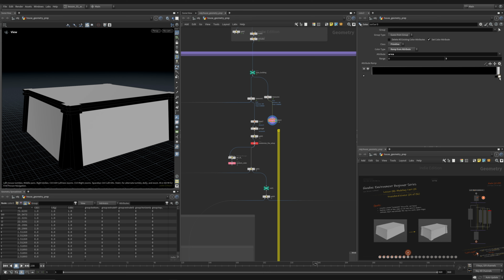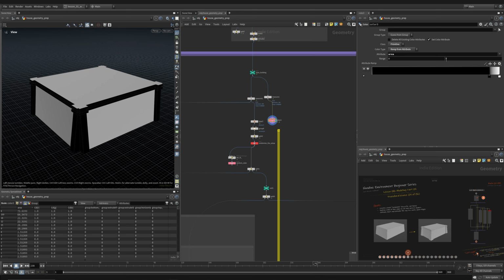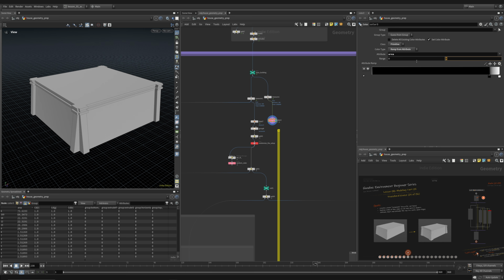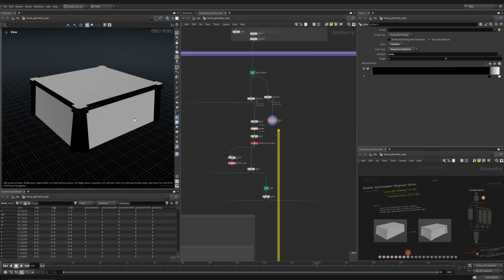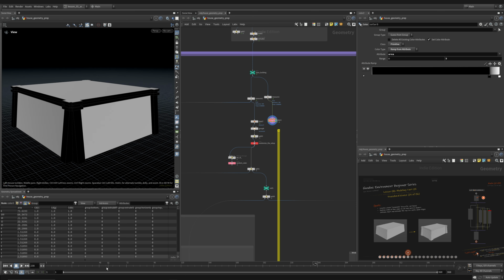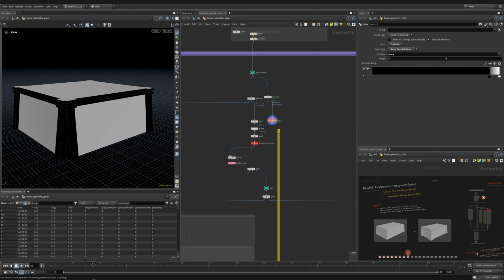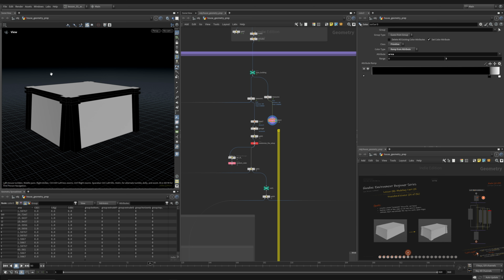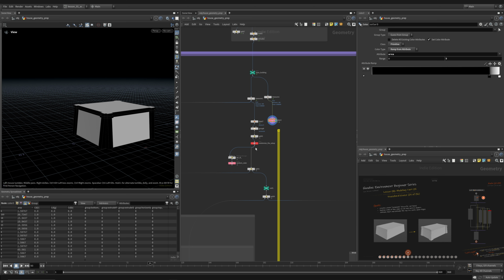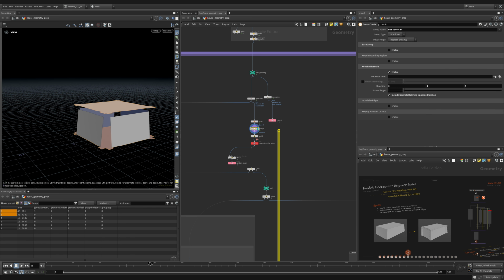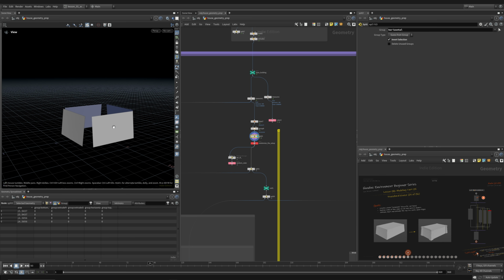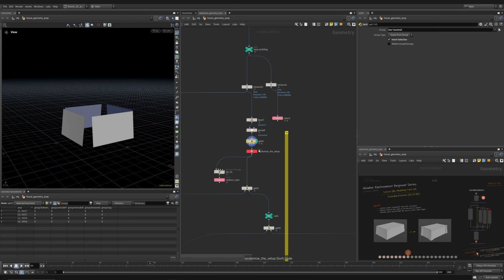And I've used this color node here to preview which ones are bigger than 5 so I can actually visualize which ones I want to keep. So by sliding this ramp input, I can change which values here are being remapped to which colors. And 5 was a value that I found across all of these randomized sizes that would give me the top of our building as well as the 4 main walls of the building. So then I'll group by horizontal. I split, so I actually don't need these roof and bottom anymore.